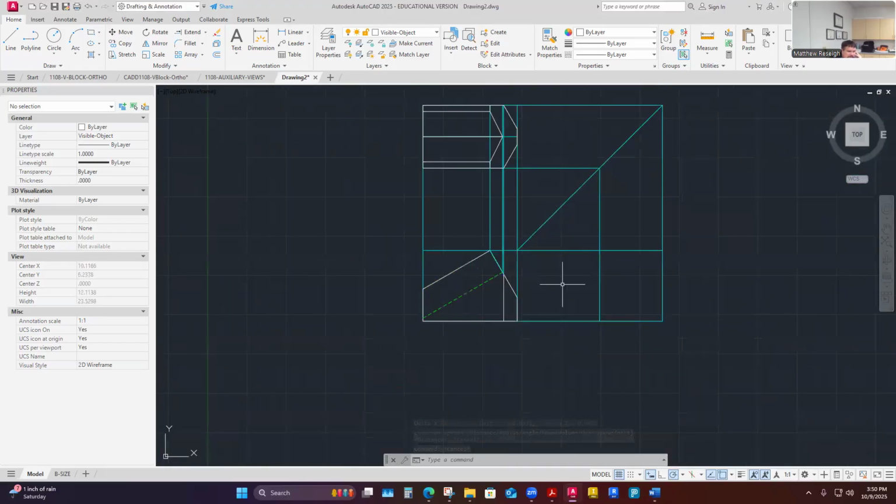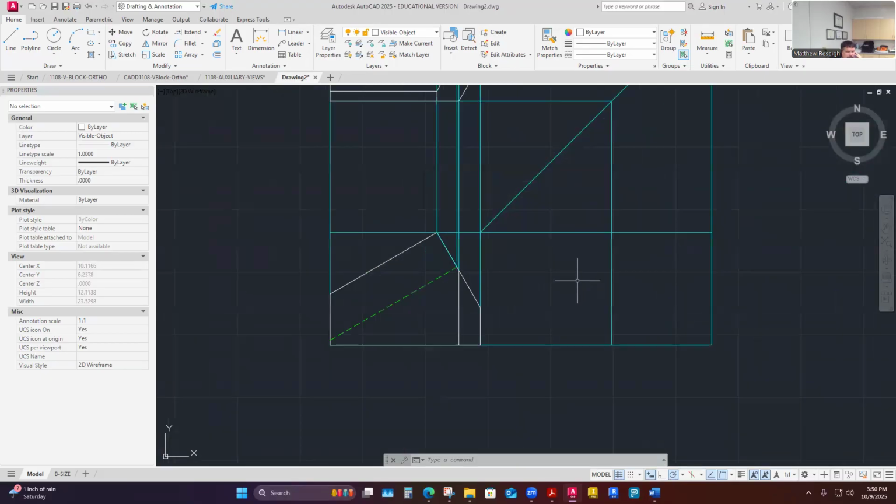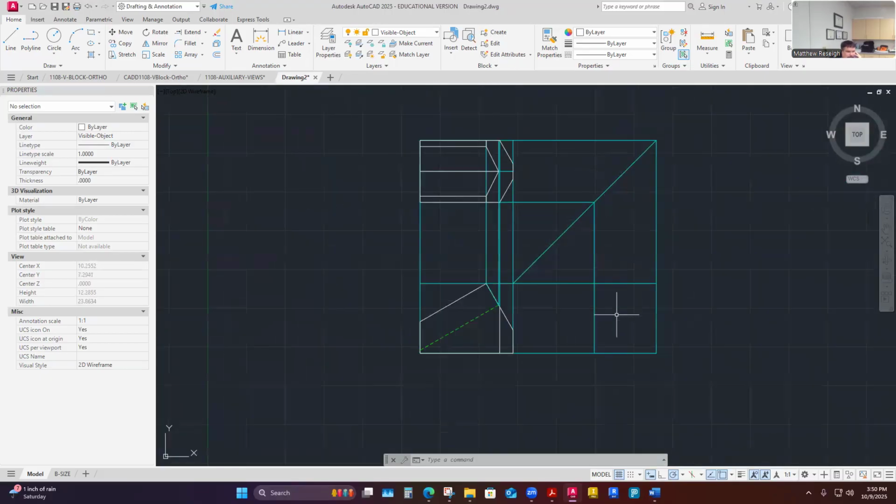So what I'm going to say, based just off this assignment, is I'm going to forego doing any detail work here. I could project all this down, but I would just get a lot more foreshortened surfaces. I would get one little rectangle that is truly dimensionable. That little front rectangle, where the right side surface is looking perpendicular to, is the only one I would carry over. I can pull this height dimension right there, and I can pull the width or depth dimension right here.